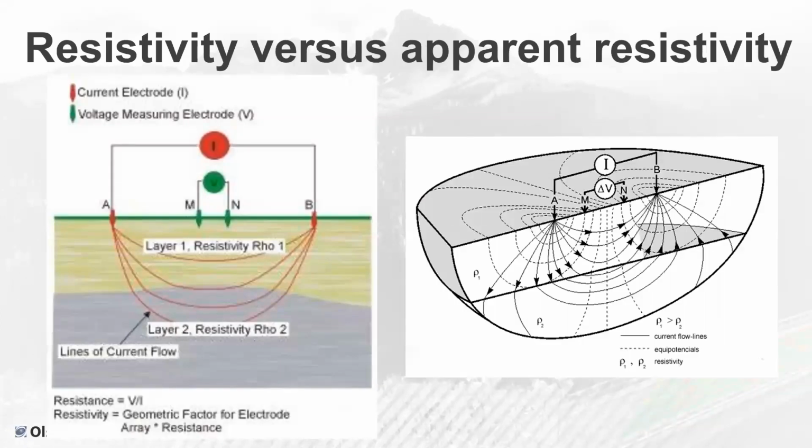Now, here's a sketch of a resistivity setup just using 4 electrodes, 2 current electrodes, 2 voltage. It's just to indicate that for electrical resistivity tomography, how we calculate the resistivity is a function of the array. And the array is just the geometric description of where the electrodes are located relative to each other. For each array, there's a geometric factor. I also use this one to indicate that most resistivity surveys done for embankment dams are profile 2D, but resistivity is always a 3D phenomenon.